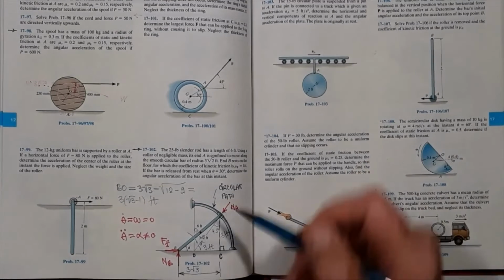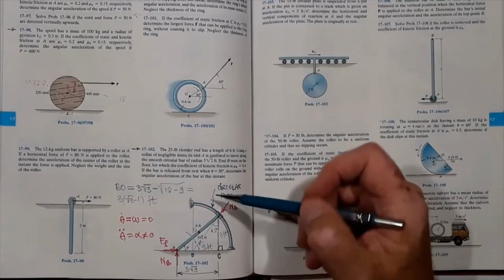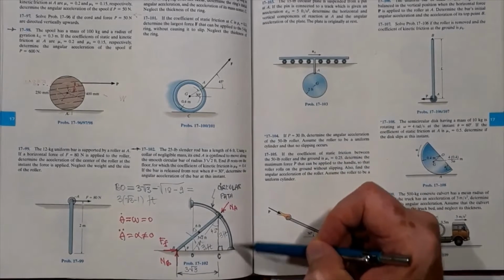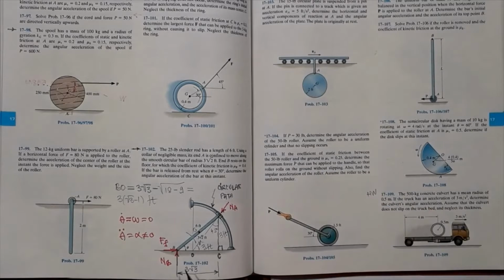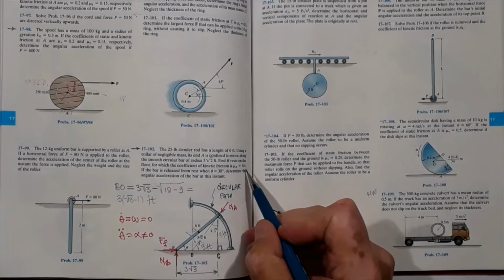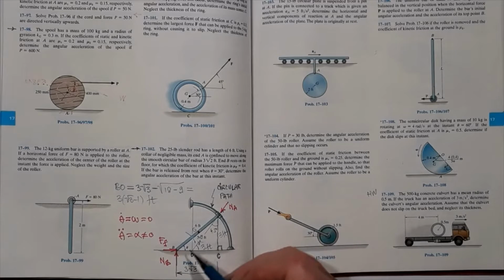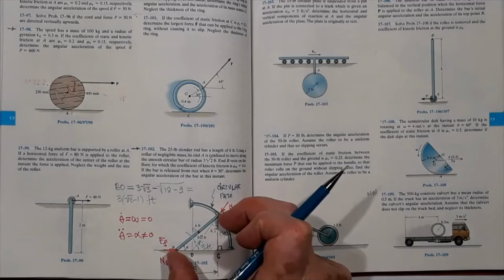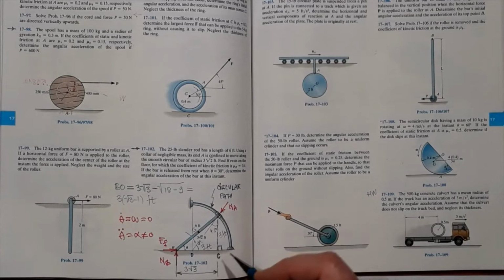Okay, so I'm going to solve problem 17102. It is about a slender rod. It's guided with point A along a quarter circular path, and B slides on the ground horizontally. There's friction at B. Coefficient of friction is 0.4. And then we have the length of the bar and the weight, 25-pound weight and 6 foot long. The circular path is 3 square root of 2 foot radius. Okay, it starts from rest when theta is 30 degrees, and we need to calculate alpha, the angular acceleration for